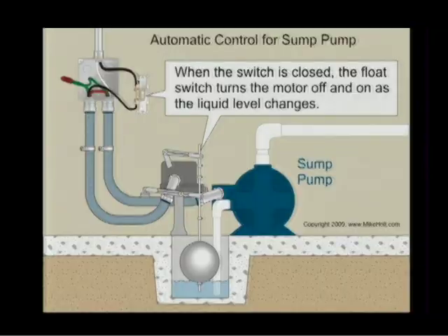So let's try to work toward this. Okay, this motor should run if the switch is closed, and if the overloads are not open, and if the float switch has risen to a level that closes the contact. Then you would have voltage to the motor. Not that the motor's running, but then you'd have voltage to the motor.